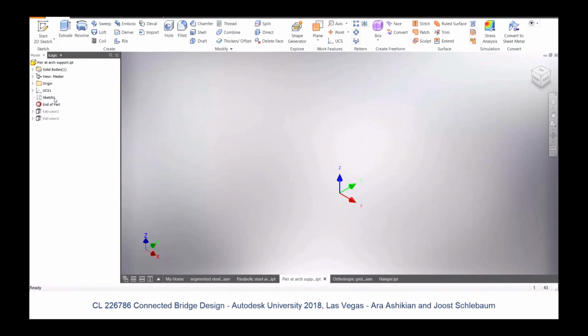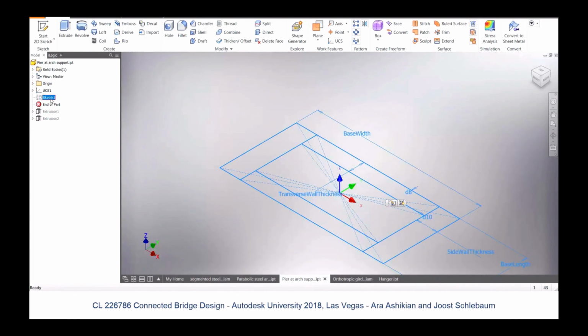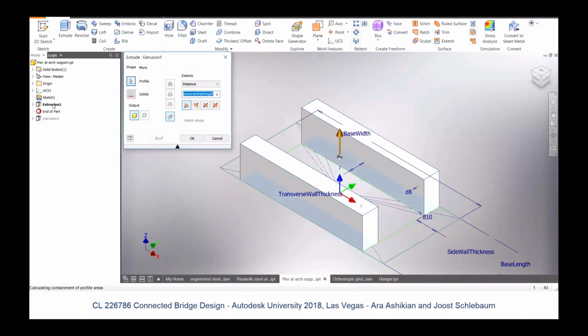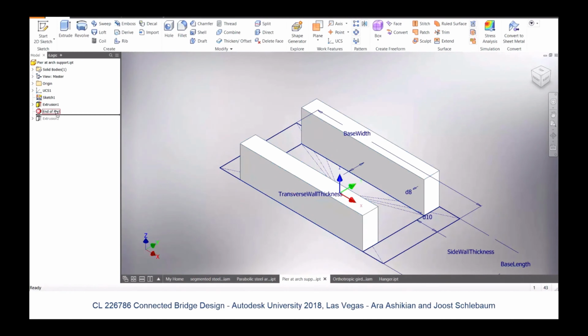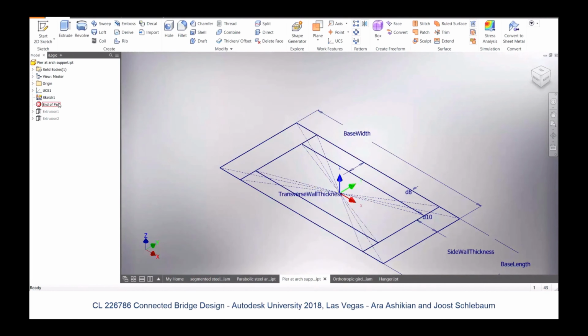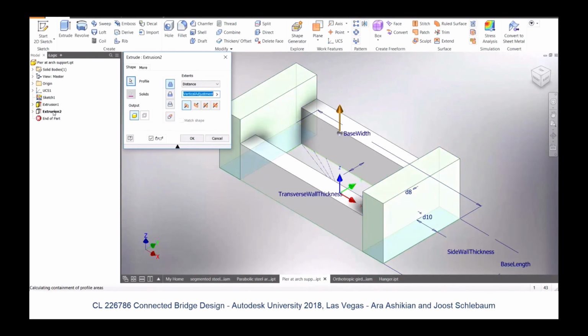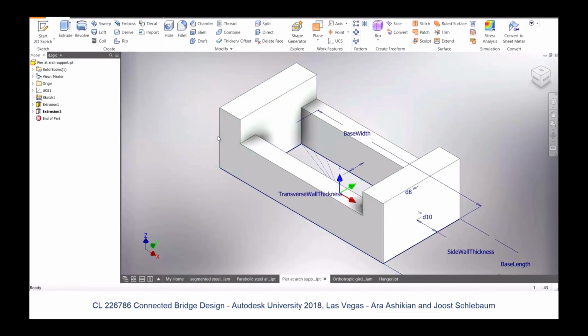And the latter part of this video shows just going into Inventor. Inventor is a super powerful modeling tool, and it's history-based. So if you open up an Inventor model from someone else, you can go up on the left and drag the history up, and you can see the sequence of modeling. Here you can see it's just a sketch with simple extrusions. I'm going to go into something slightly more complex. Modeling in Inventor is a Cadillac modeler compared to modeling in Revit families or Adaptive. You can model directly on top of geometry.